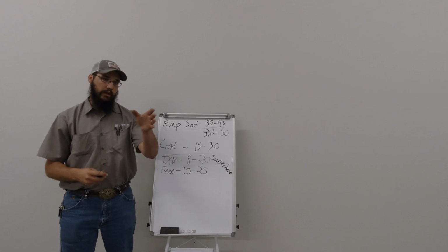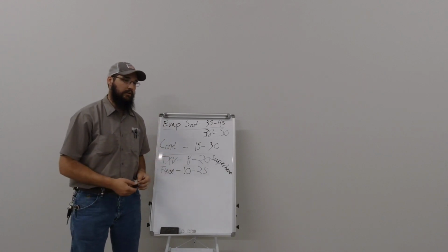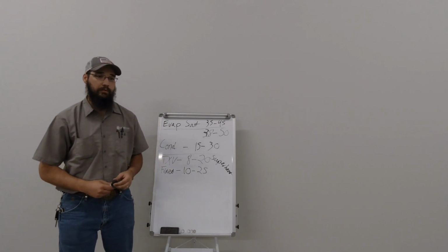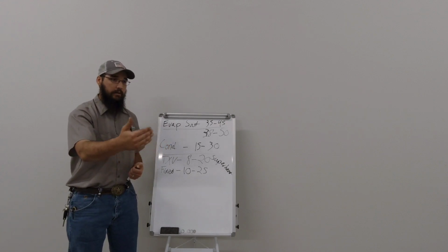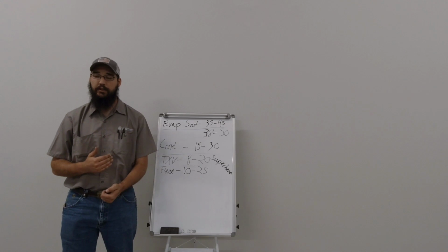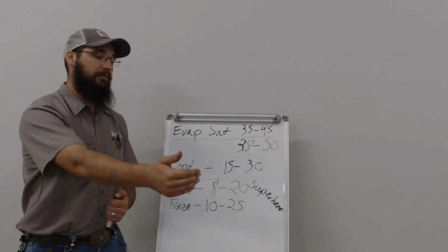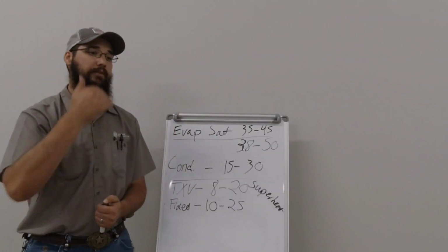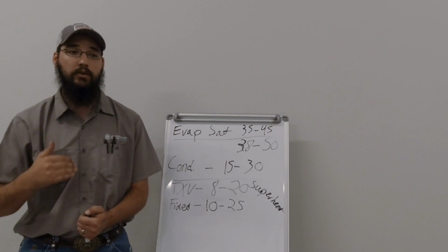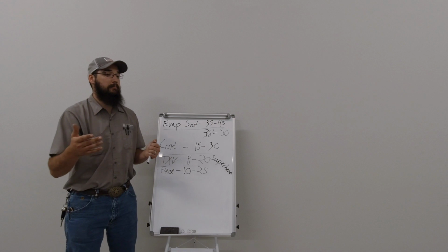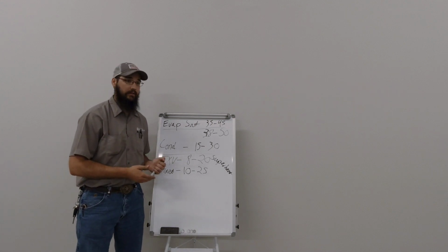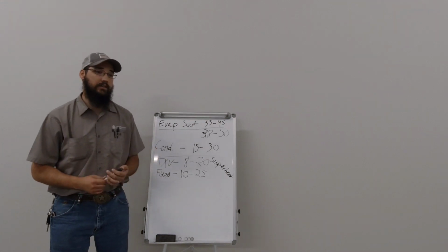So to your specific question, you have three compressors, all of them running together, they're running a 25 degree superheat. At that point, that would be justified because you start looking at the load condition. So if you've got 25 degrees with three compressors, you've got enough load on the coil to support that. Now, would I love to see less superheat? Yes, but that may not be feasible depending on the setup.